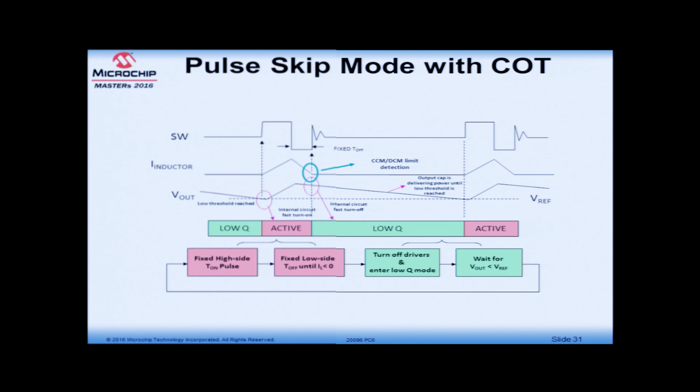So, whenever they go to the light load, they generally provide another comparator and skip the usual path to make it light load efficient, but the transition is not smooth. But in the case of constant on time, there is no amplifier in the path and there is already a comparator in the circuit. So, we make use of that comparator to get the pulse skip mode.